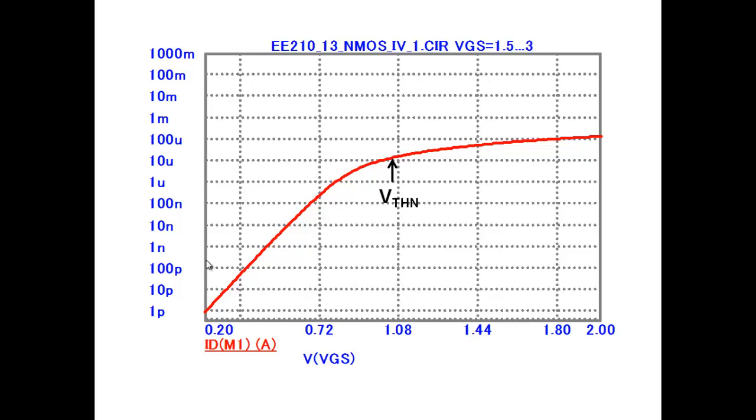This is an extremely important thing that happens when you try to scale, because as you scale the MOSFET, we'll see later on, you have to scale the voltages also to manage the electric field in the system. If you simply scale the channel length without scaling the voltage, the fields become very high and the transistor characteristics are no longer proper. So as you scale, you also have to scale the voltage, and as you scale the voltage, you'll have to scale the threshold voltage also. So these characteristics shift left, and what you start getting is increasingly more and more current here.